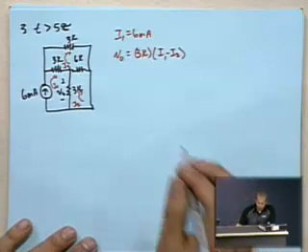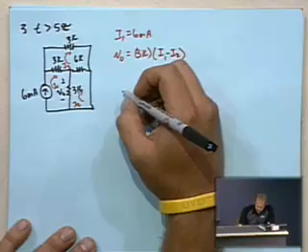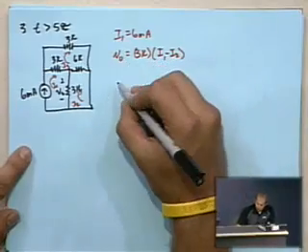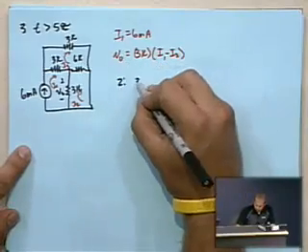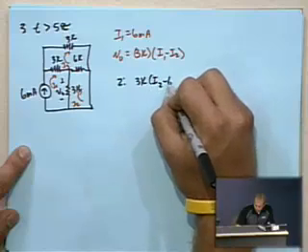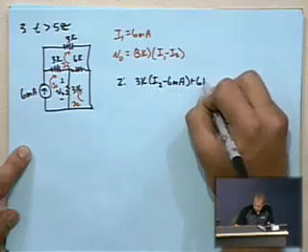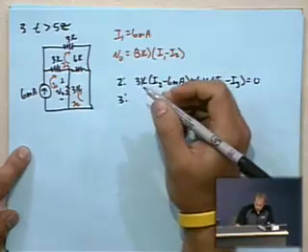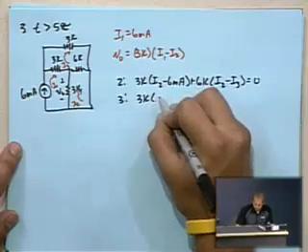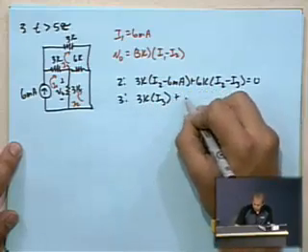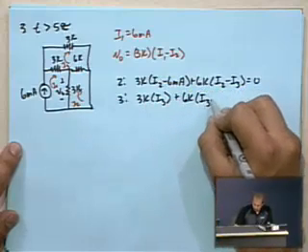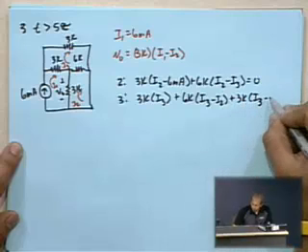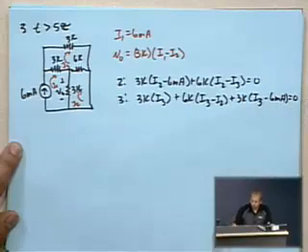I'm going to put down the original forms of the equations and then the solution. Around the second loop, you have 3K I2 minus 6 milliamps plus 6K (I2 minus I3) equals 0. Around the third loop, you have 3K times I3 plus 6K times (I3 minus I2) plus 3K I3 minus 6 milliamps equals 0.